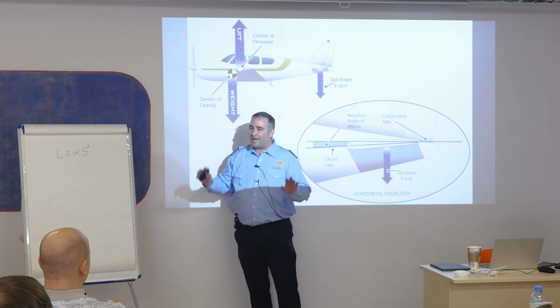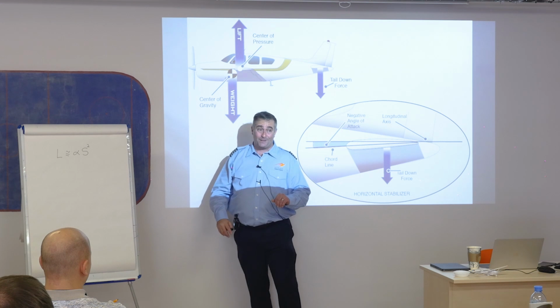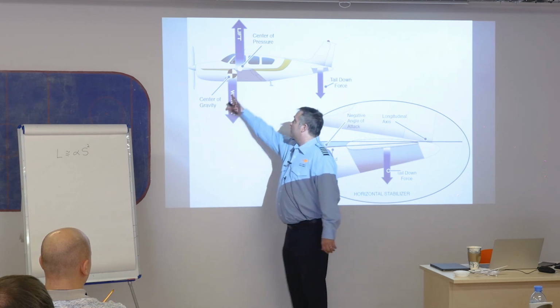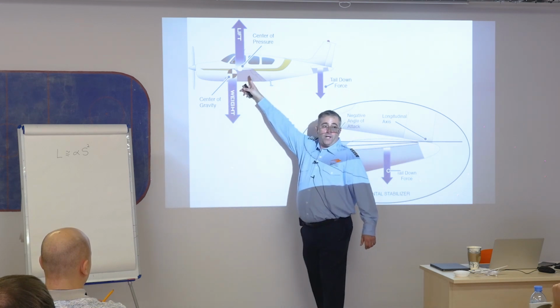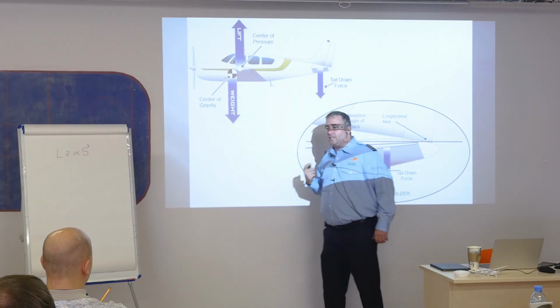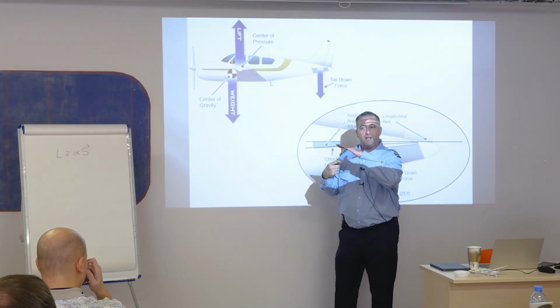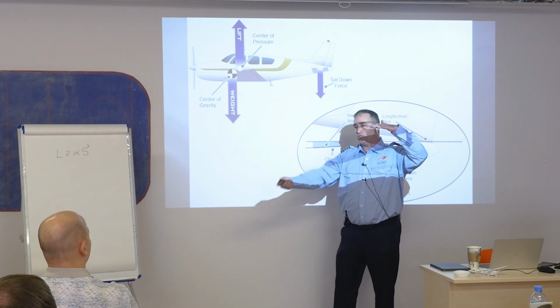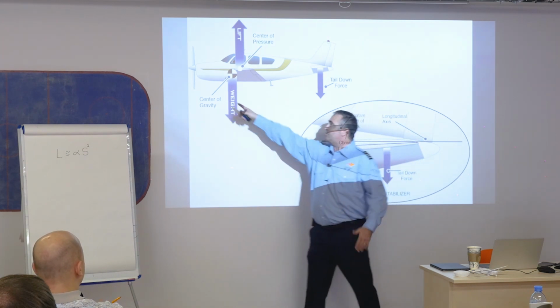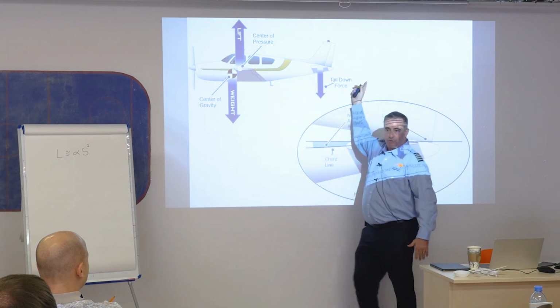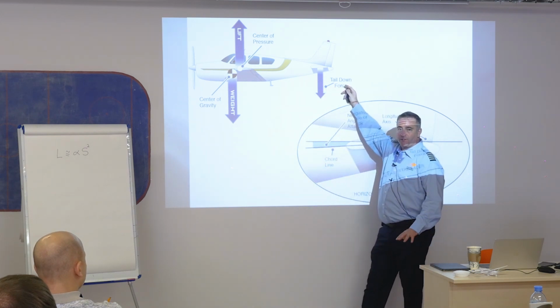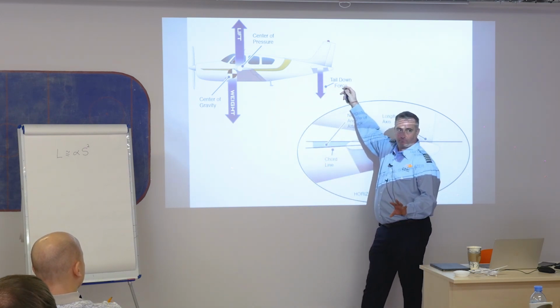I get it. It's not a jet engine, but it's producing a substantial amount. So the relative wind is affected as soon as I decrease the power. The airplane right now is flying the same speed because I just reduced the power. But this fan is blowing less over my control surfaces. Okay, we all agree? That's called the accelerated slipstream.